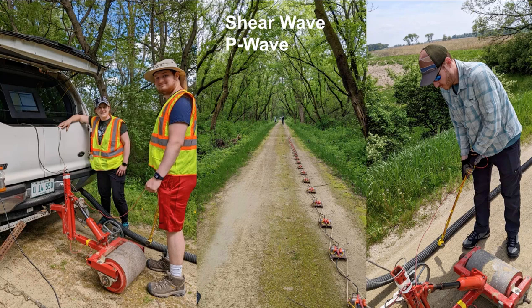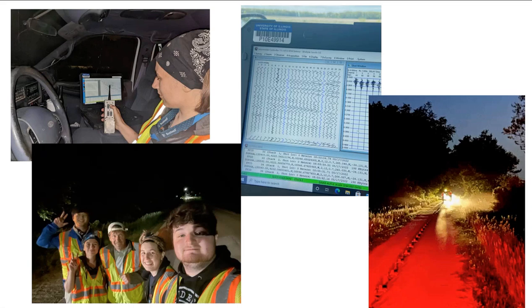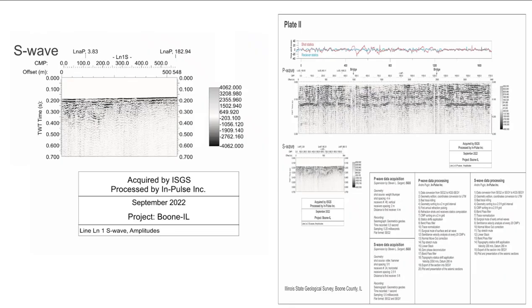We ran 7 or 8 miles along the trail. Our student crews were working in the middle of the night sometimes to avoid traffic. So they have a bunch of geophones behind a truck and can measure seismic waves in the field and then come up with profiles of squiggly lines that myself and geophysicists can interpret of where the bedrock surface is. So I don't have full interpretations of those, but these are some of the data.